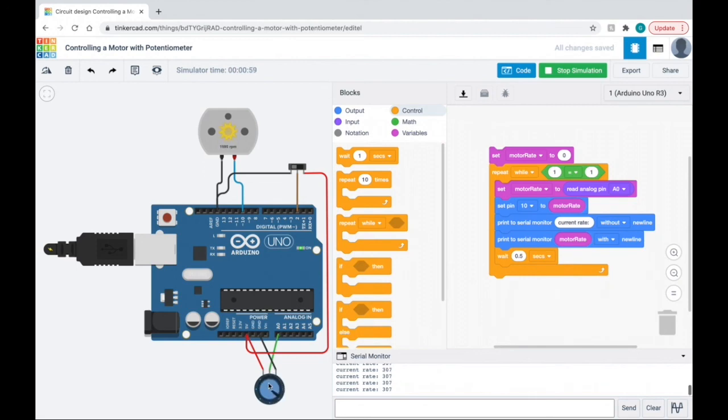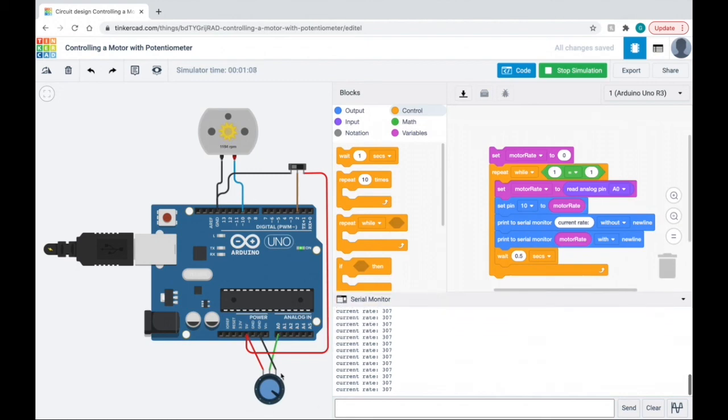This is because the input we get here is a bit more complex than we want to talk about in this course, but what's happening is the potentiometer input to A0 is represented by 10 bits, which corresponds to up to 1,000, as you could see, 0 to 1,024. But the input the motor is expecting is between 0 and 255. And basically the number is being truncated to that many bits, and that's why it rolls over and starts from 0 again for the motor.